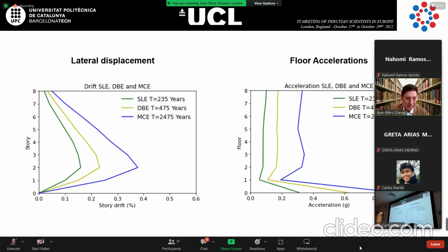And then you can see my results. For example, on the left is the lateral displacement. Keep in mind, my building has seismic isolation. For that reason, the displacement is much less in contrast to another building without seismic isolation. In my case, the lateral displacement is so small, for example, in the drift. The drift is a term in engineering. It is 0.3 something. In centimeters, it is like 1 point something centimeter. It's so little. But if you don't have any seismic protection system, maybe your displacement is 30 centimeters, 50 centimeters, or maybe more, or maybe collapse.